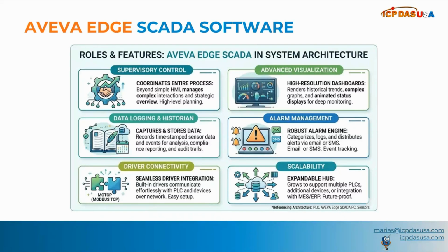Connection to equipment is done through drivers, as there's an extensive driver library, and you can also create your own drivers. Built-in drivers like Modbus TCP allow for streamlined communication with field devices, and our ICP-DAS Modbus TCP-based Ethernet I/O modules. Remote monitoring systems are very scalable and easily integrate with cloud and other systems.